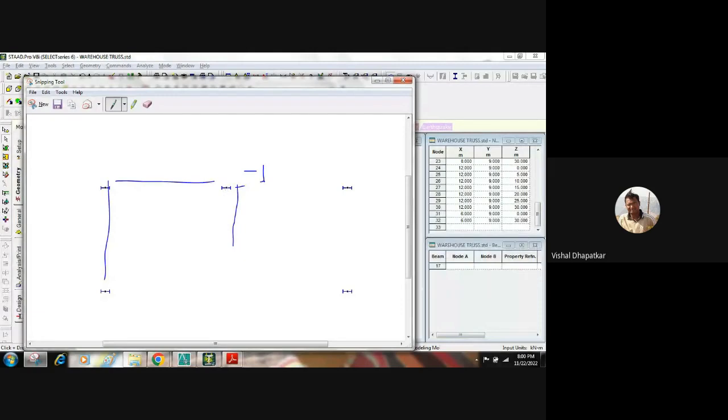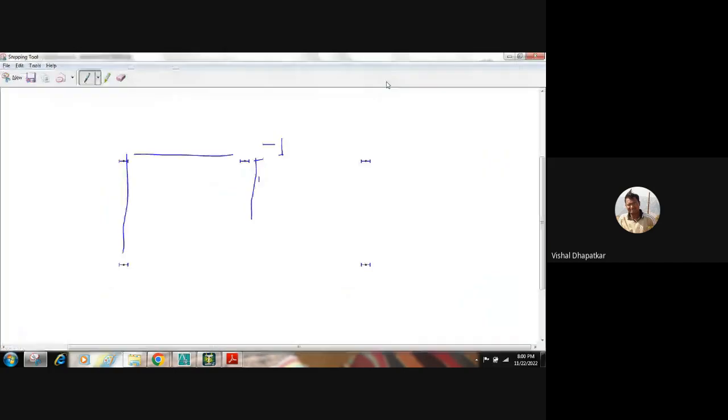So in order to have the major axis in the direction where we do not have a tie, that's why we have to put the column like this. We can tie in this direction, but we cannot tie in this direction because the other column is at 30 meter length. That's why we have to rotate this column in this direction. Why do we need this column in this direction? We can also rotate this one. We have a tie on the top also.